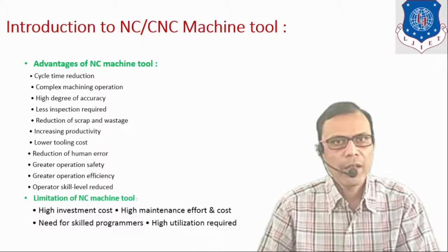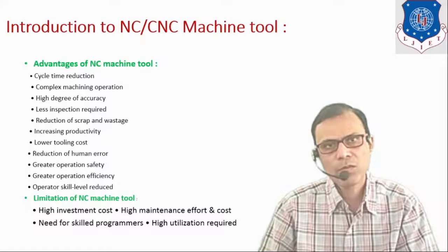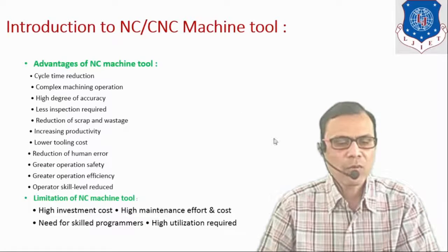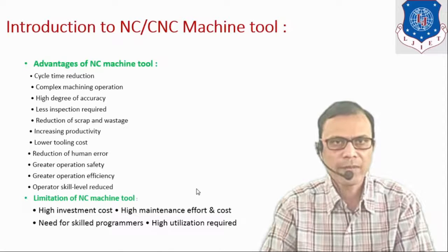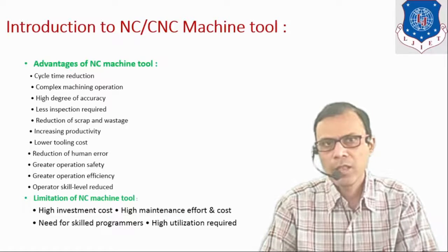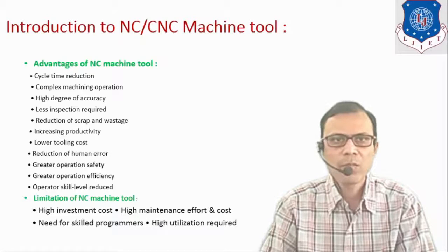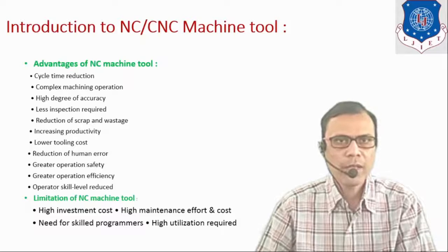machine tool, and its maintenance cost is also high. It requires a skilled programmer, and high utilization of the machine tool is required, as to produce one part it is not economical, but if we want to produce the same part in large quantity, then it may be economical to use NC-CNC machine tool.